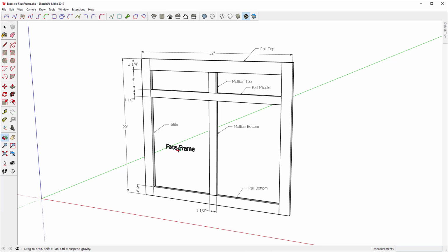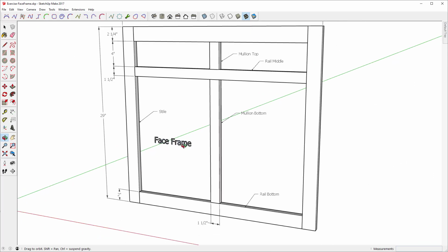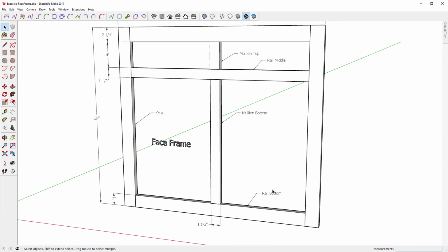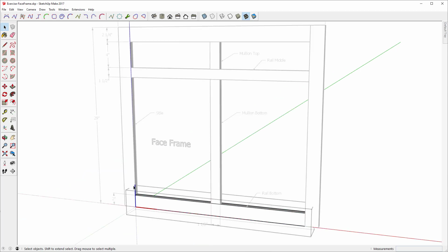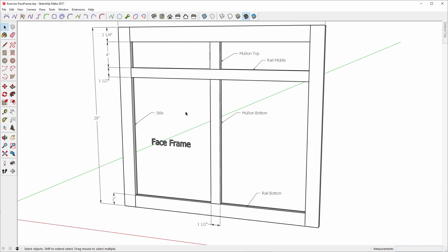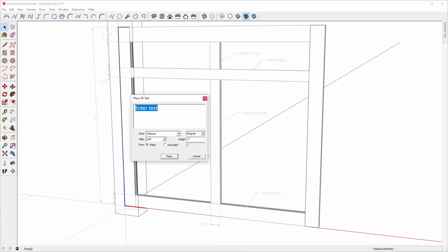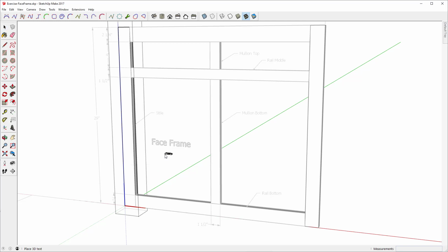I could also, if I wanted to, instead of labeling each part like this, open this for editing, and tell you what, I'm going to do the style. I'll open it for editing, and we'll call this style. I'm going to make it a little bit smaller. And just to show how this works, we'll extrude it 1/4 of an inch, and I'll place it like that.